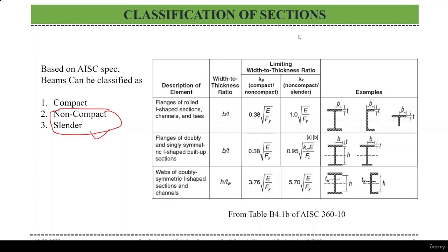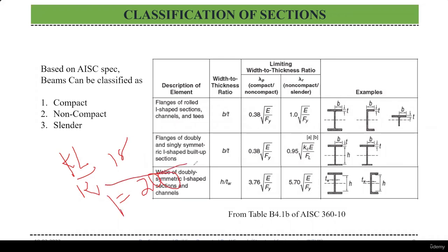Sir, one question. Yes, tell me. There is a limit for slenderness also, no? Like, for example, sometimes in STAAD it will show. Yes, for sure. For example, KL by r, the slenderness ratio, will be limited to 180. In some cases, for flexural cases and tension cases, we'll use 200 according to AISC.